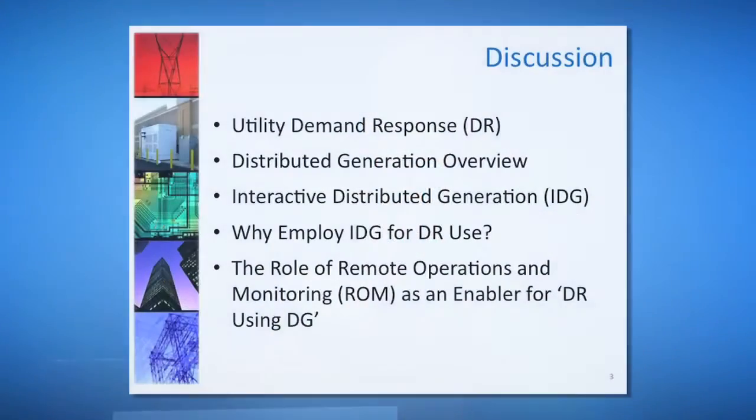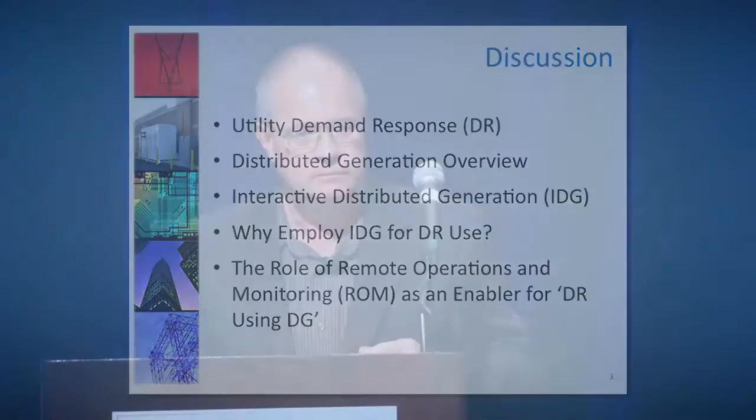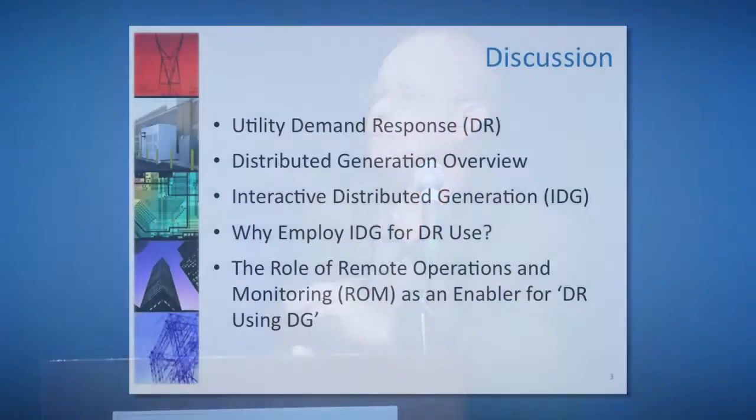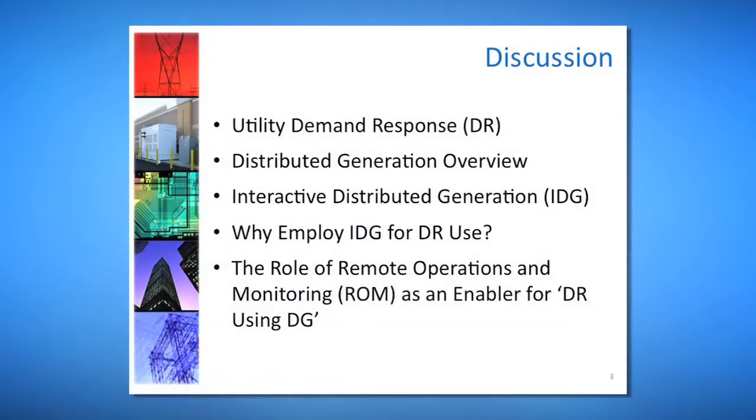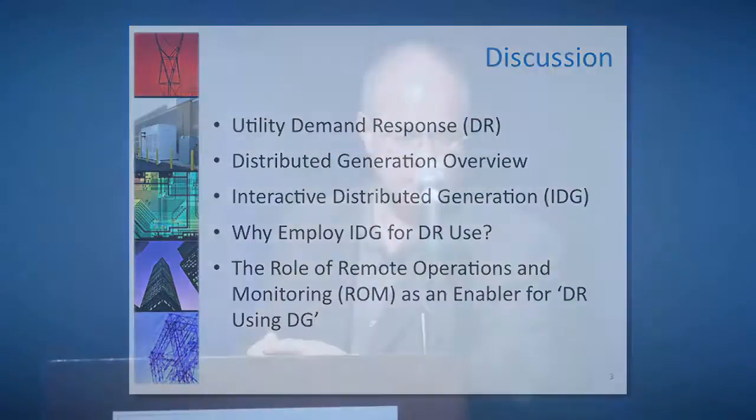The demand response windows are often very short. Typically they can last an hour, be even less, sometimes up to 2 hours. That's really where these critical peaks are in power system demand. Then we'll look at why employ the IDG. Right now, most people, if you said, what's demand response? Turn it off. You wouldn't say, turn on a generator. It's almost counterintuitive. But if you can remove load locally, that's why you want to go and do it. Then we'll look at how the remote operations management dovetails in and makes these systems operate.